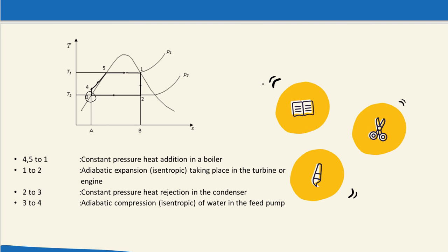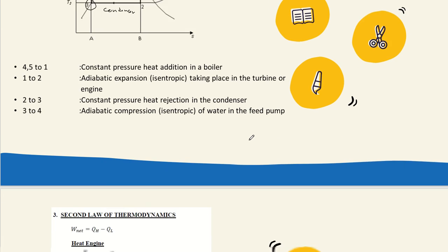Actually, the process in the power cycle in both cycles for Rankine and Carnot is the same. For the Rankine, we also have boiler, turbine, condenser and pump. The difference is the region for state 3, which for the Carnot cycle, as I mentioned earlier, the region is a mixture of liquid vapor. But for the Rankine cycle, the region is saturated water.